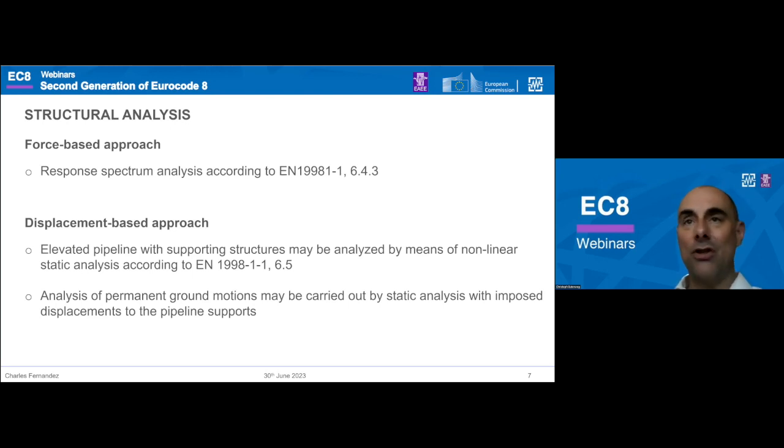As I already mentioned, this is a standard procedure in part 4, but a displacement-based approach is also applicable by nonlinear static analysis for the supporting structures. So there's no reason against it, but we have to keep in mind that we have to handle the differential displacement that can occur between the different parts or along the pipeline.